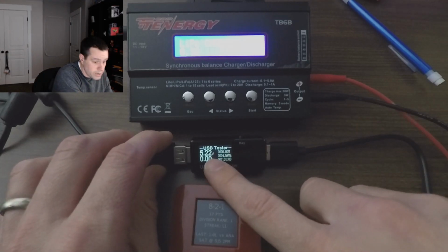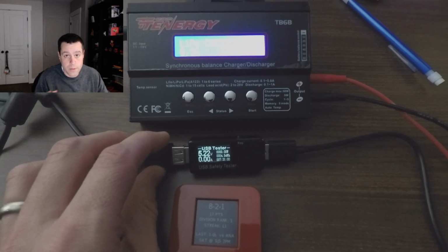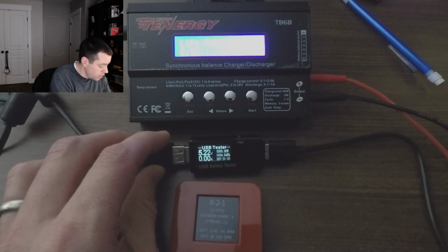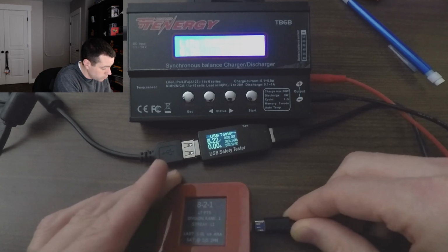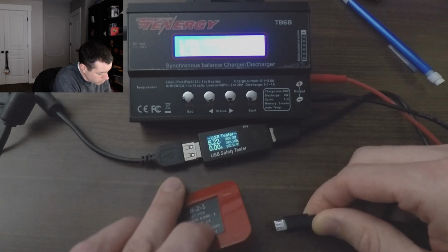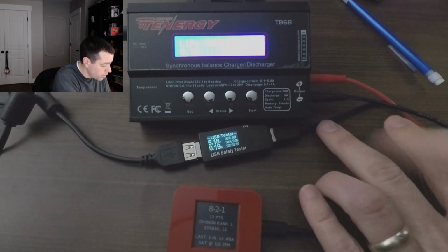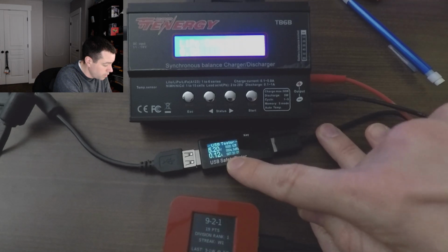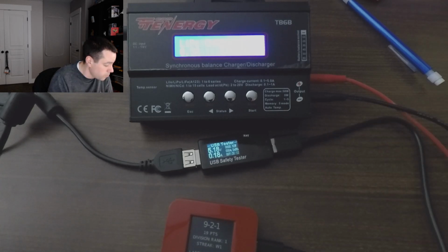You can see right now I have this connected to a charger. This is not connected to a laptop, so I won't have any current limitations in that regard. You can see that it's sitting at 5.22 volts, 0 amps. So what we're going to do is just plug this guy in. Okay, little flash. You're going to see the current, 180 milliamps. It updated, 180 milliamps. It's sitting at 180 milliamps right now, and then it should go to sleep.